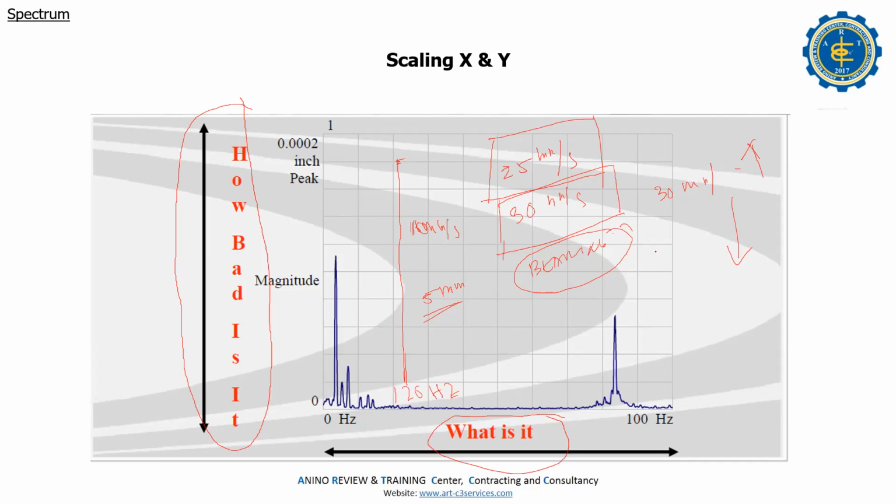Now, the maintenance call, high vibration. I will take a reading, 30 mm per second. Then after 1 hour, I will climb, then go down to 5. But the important thing there is the bearing. You must monitor the bearing.